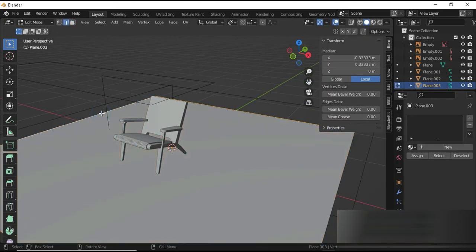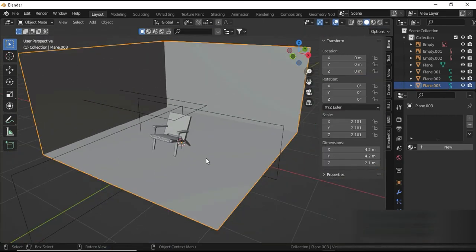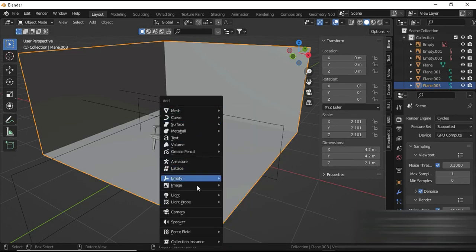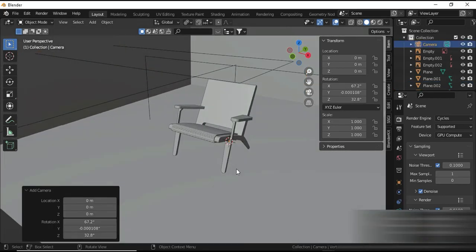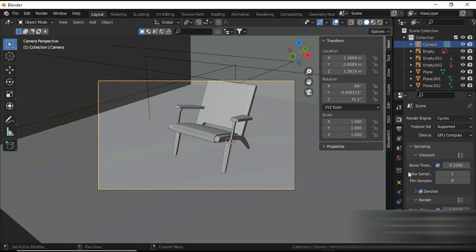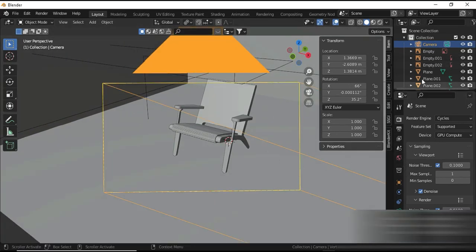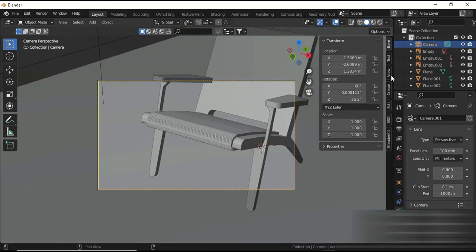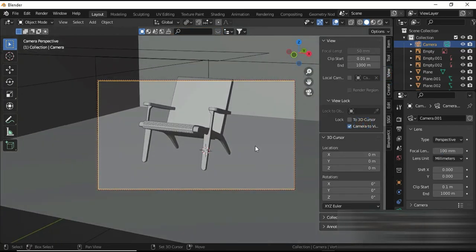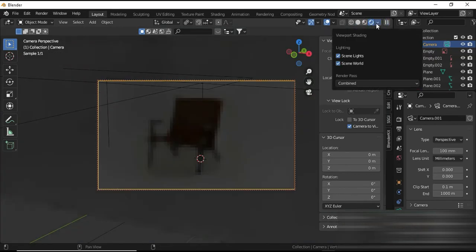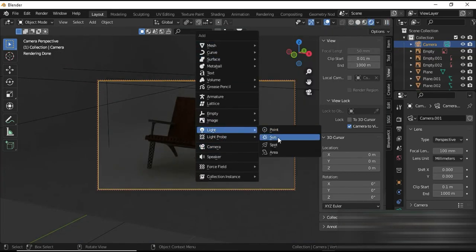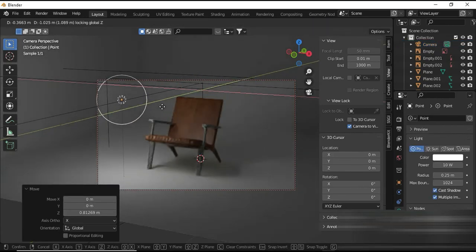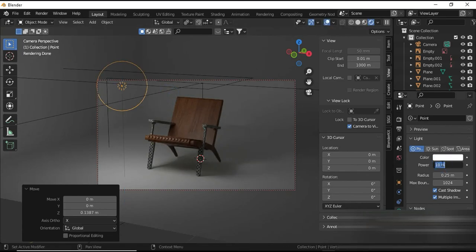So now I think it's the final setup, the final studio lighting and the setup. So guys, I hope you enjoyed this video. I hope you learned something from it. It was quite fun making it, and we learned quite a few different concepts. Another important thing is the color management. Make sure it is Filmic and high contrast. High contrast is going to give you a lot of realism. That's an important step. And now it's just adding the lighting and making sure the camera is correct.